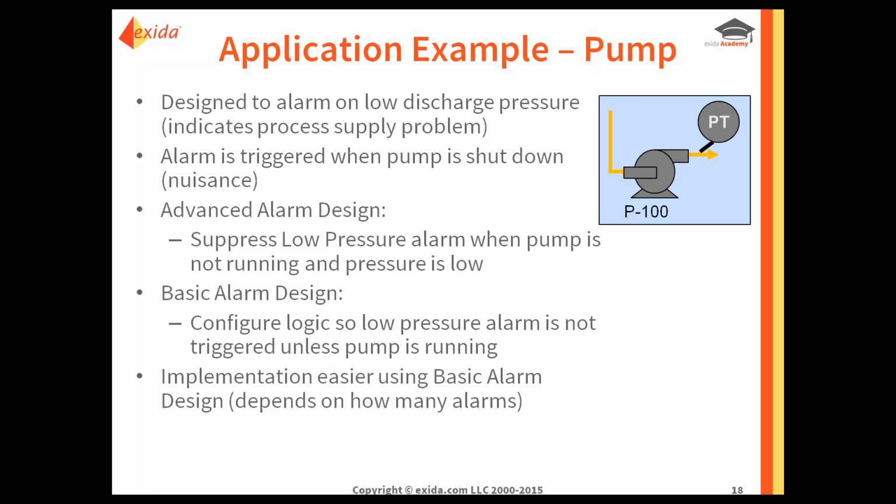That alarm would actually appear on a suppressed alarm list, or should appear on a suppressed alarm list. And that is very different than if you had applied a basic alarm design technique, which steps back and says, let's configure the logic to be smart about when it generates the alarm.